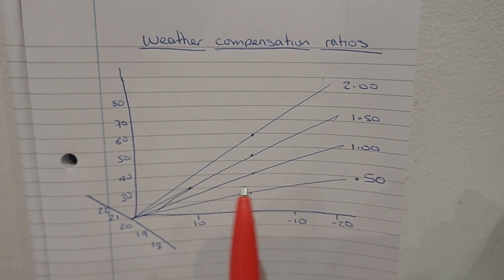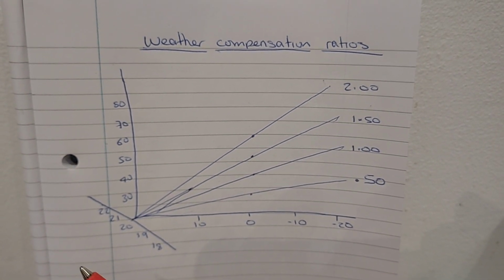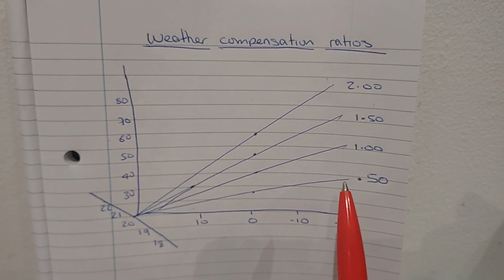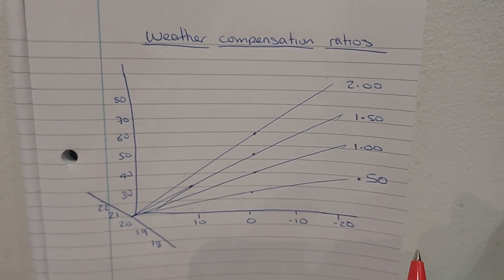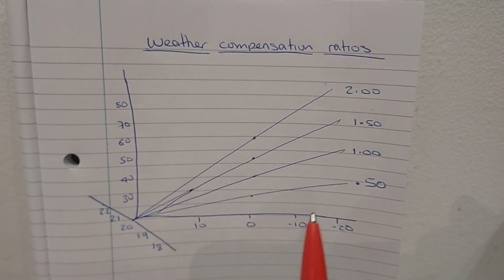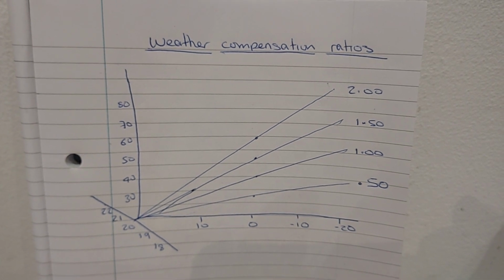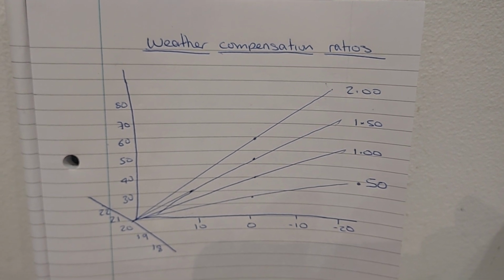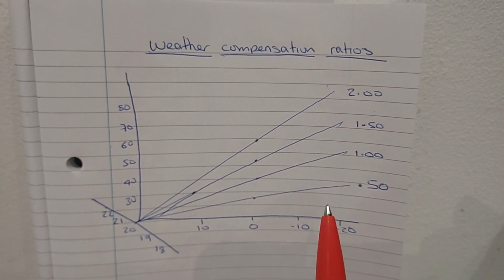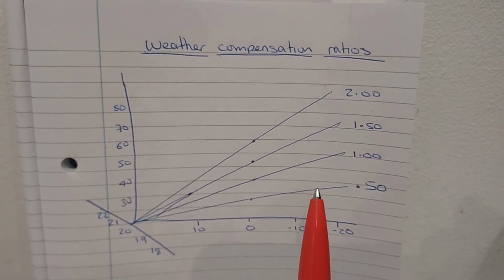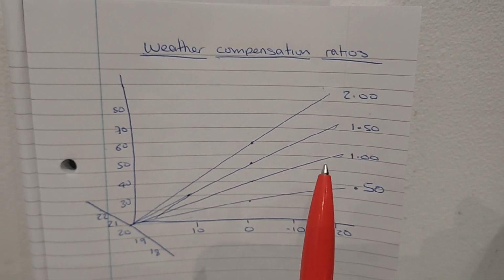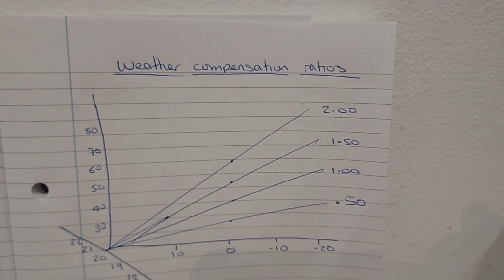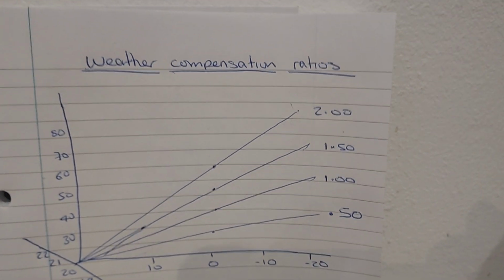People talk about insulation on systems with heat pumps. Now this is where it matters on underfloor heating, because we're trying to get down the number of watts per square meter required to heat a room, and we've got very limited capacity on an underfloor. We can only go to a surface temperature of 29, and that gives us a certain number of watts per square meter output from the floor. And so if we can't make it, the temptation is to turn up the temperatures.